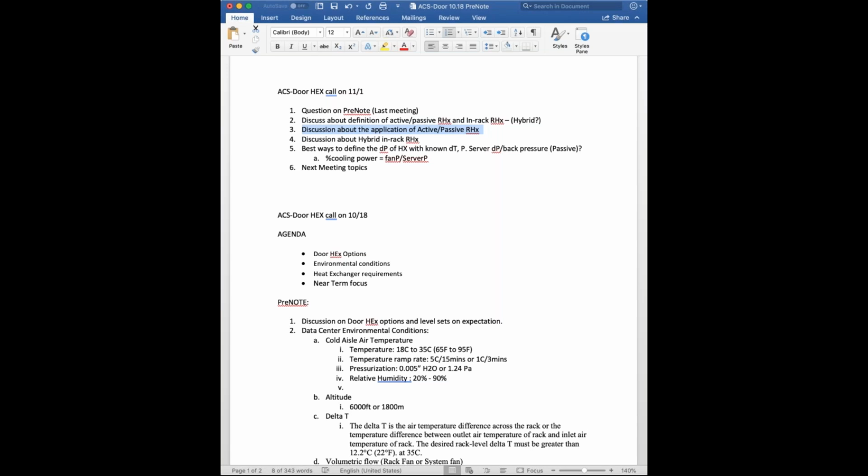Yeah, here, Ronald van der Zwaan, I agree. The pressure drop will increase the amount of energy used by the IT fans. That's true, but you lose the fans that you normally have in your air handling units, and the air loop itself is much shorter, so there's less energy needed to move the air from the cooled air back into the IT equipment. So it's a relatively short loop. And as long as you keep it passive, you don't need controls, you don't need electrical connections.